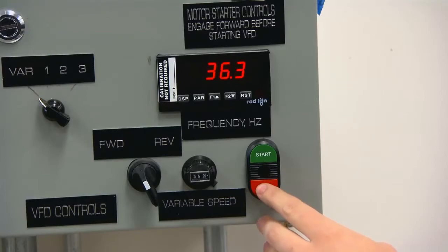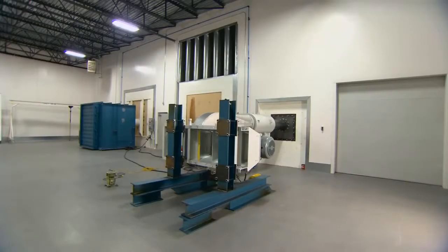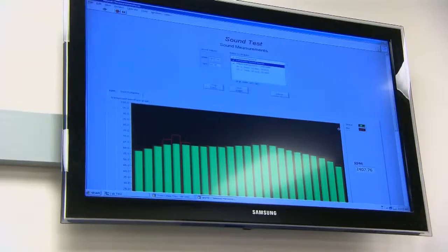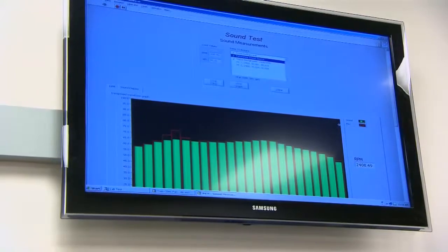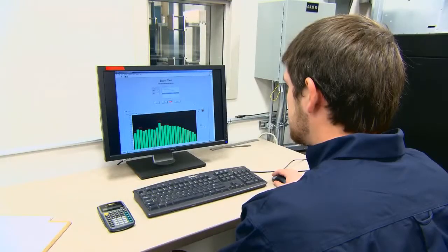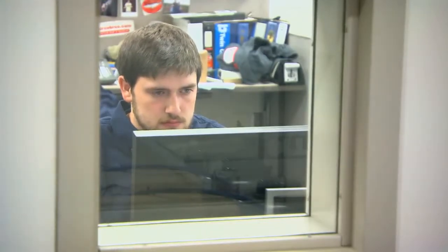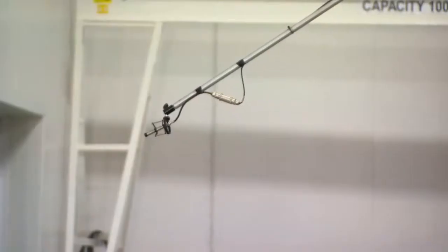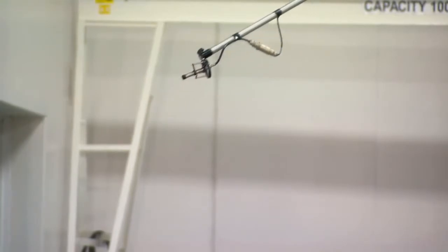So once you determine the sound power level of a test fan, we take it and we post-process the data in our engineering tools, which we use to bring in multiple tests into that tool so that we can do further post-processing and analysis that is required to see, okay, what are the frequencies at which the sound level is high?